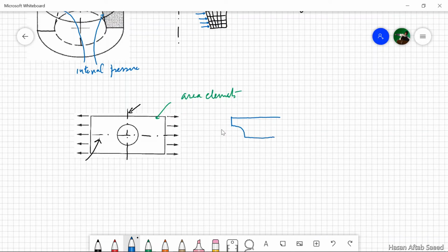If we model this body like this, we apply the loading on this part, its fair share, and what we need to do now here is we must constrain this problem. Now here, this line, the displacement here is 0, because the nodes on this line neither go to the left nor to the right, because again there is symmetry on both sides. So the u displacements, the x displacements, are 0 on this line.